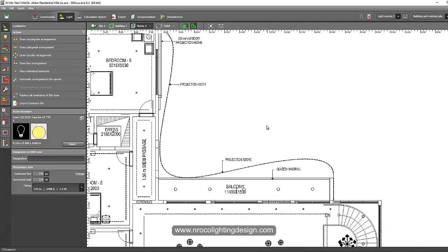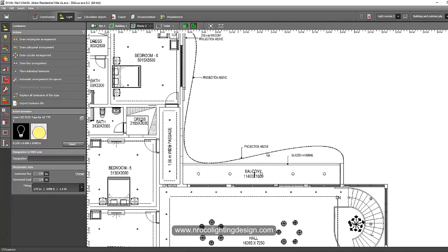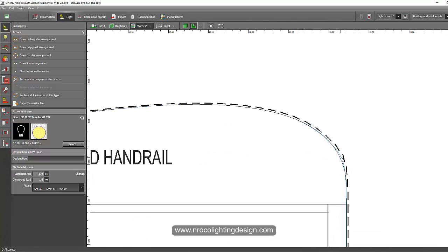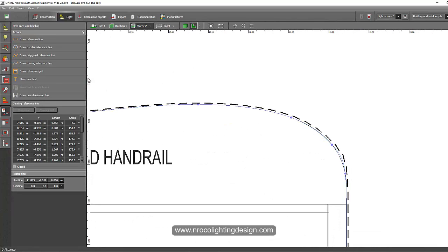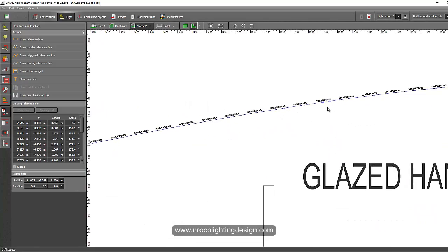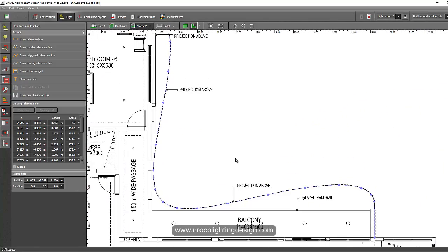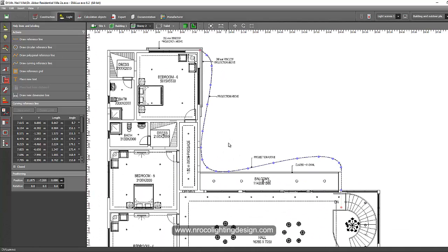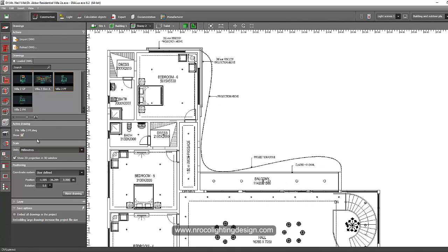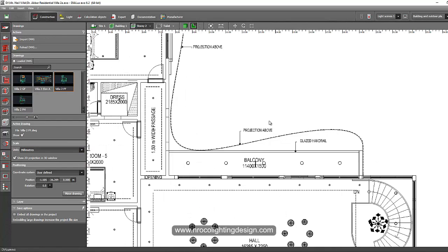So what I did, Elisa, is very simple. You have your curved roof, right? So I created a pattern or a curved reference line. So you can see now I have the curved reference line. It's easy to have a curved reference line, especially if you have your AutoCAD file. So you just have to follow the AutoCAD file. So I'm showing now the AutoCAD file.